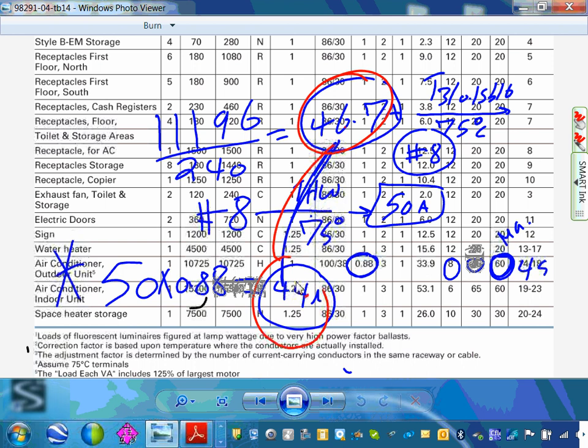Yes, sir. Are you pretty sure it's 240 volts? It has to be. Because it wouldn't make any sense other than AC, typically single family. If you look at the schedule, they're using 24120 for this project, so it has to be 240.